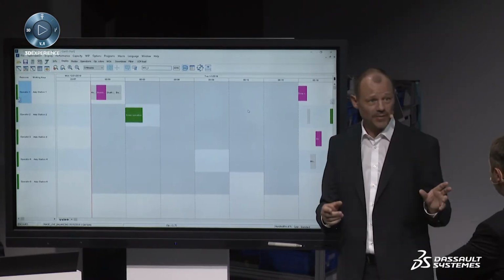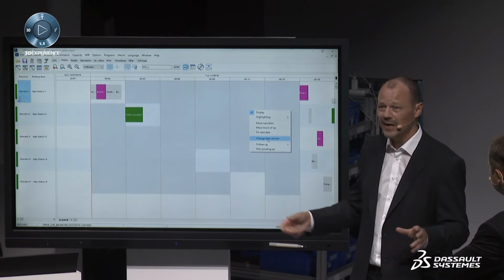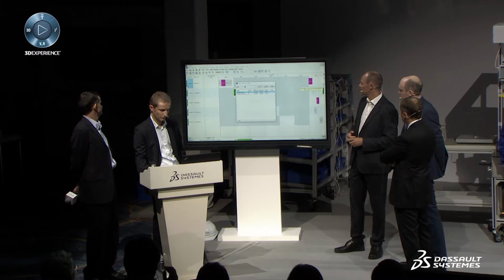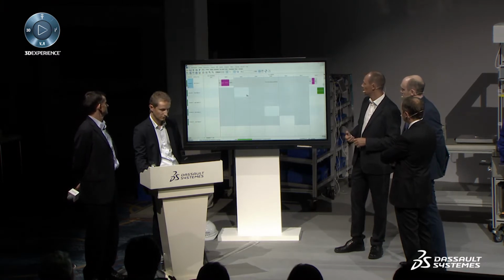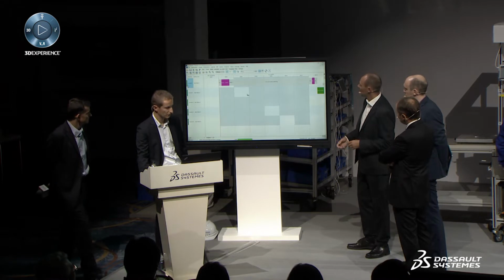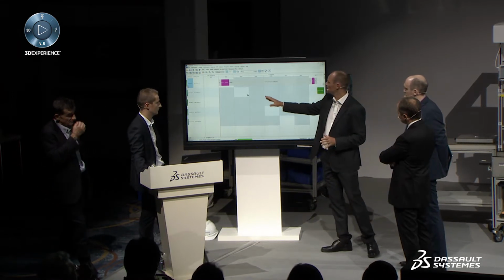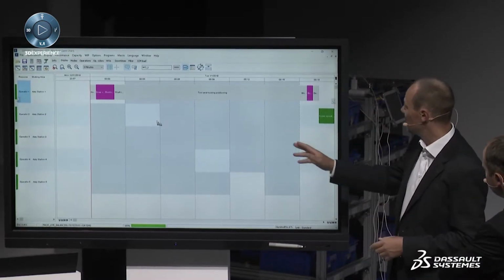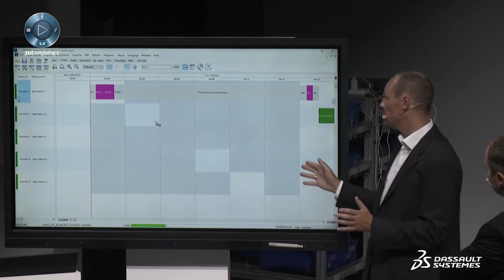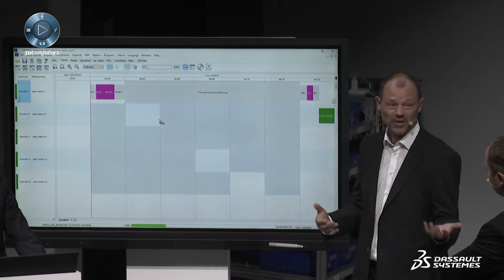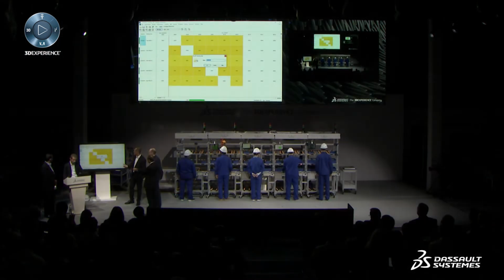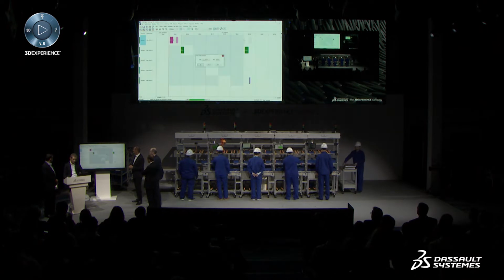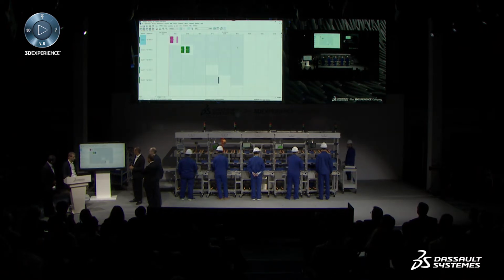What we can try is, because we have a second routing, which we saw before in our work plan, let's try if the second routing is working here. We change our simulation, our test, to the second routing, and we simulate this, and it looks a bit better because we have many more operations connected now to station 1 and 2, which are already available. But we see it is not working in our takt time. Maybe it helps when we just double the takt time from 3 to 6 minutes. Let's check what this idea brings us, and yeah, almost good. It's good.